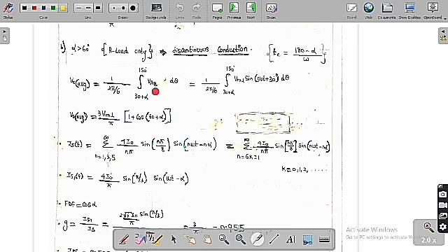So in 30 plus alpha to 150, the thyristors which are conducting are T1 and T6. So when T1 and T6 are conducting, V0 is equal to VAB. So VAB into d theta, which is equal to, if you solve this one, as VAB is equal to root 3 Vm into sine of omega t plus 30.